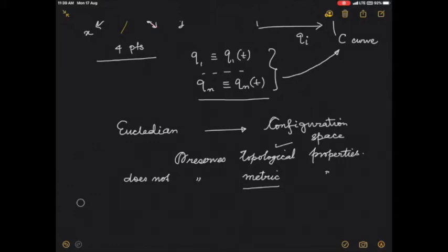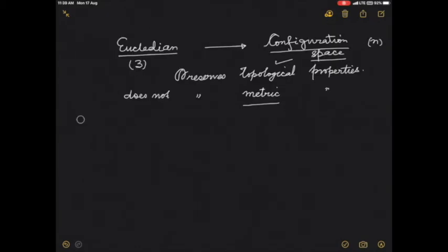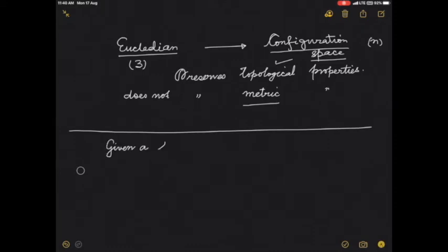And we are talking about the transformation from the Euclidean space, where we write down the original 3n coordinates, to the configuration space, which is n dimensional. So this is 3-dimensional, this is n dimensional. What other type of transformation can the configuration space have? As we said, there can be different types of generalized coordinates that I can choose, and the configuration space could be constructed in terms of all these generalized coordinates.